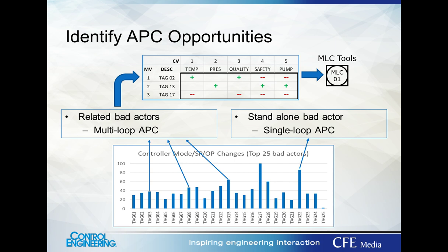This can come out of process knowledge, discussion with operators or process engineers, or may be evidenced by highly coincident interventions in the data. This reminds us of the old adage that historical data is rarely useful for modeling because operators tend to make multiple related moves together rather than one move at a time as required for modeling.